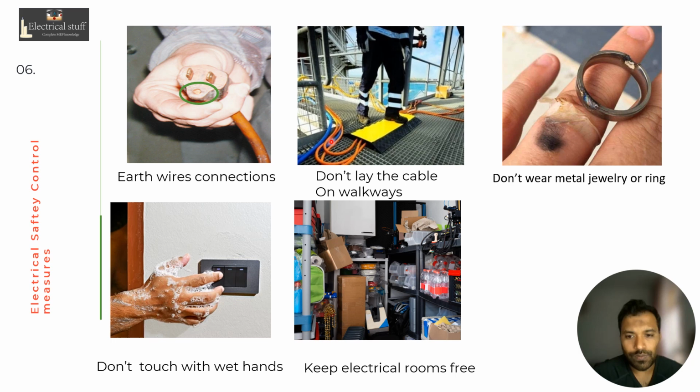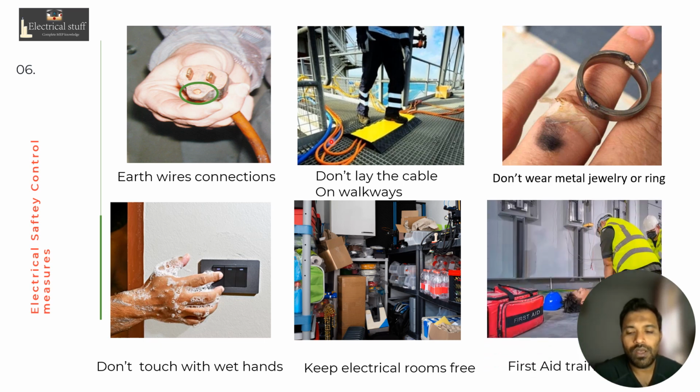So don't touch with wet hands. With wet hands, the resistance of the human body is very low. So don't touch with wet hands. And qualified electricians or qualified engineers must learn electrical first aid training.